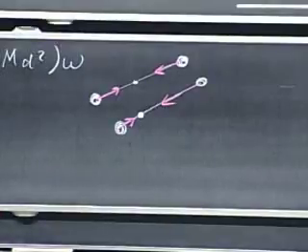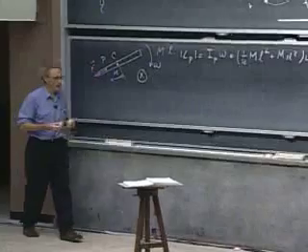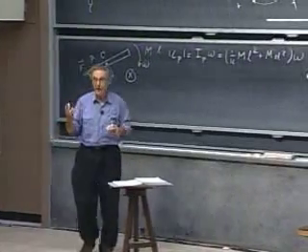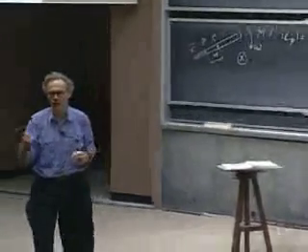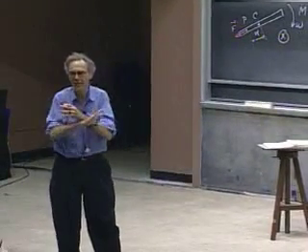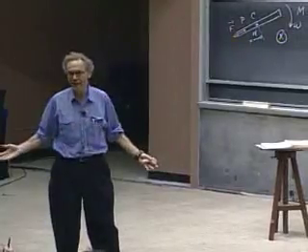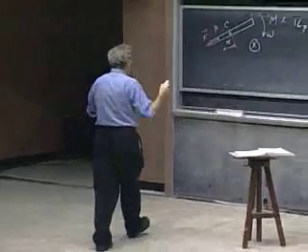It is because of the same asymmetry that you have here that there will be a force from the pin on point P. However, I don't care about that force because I'm going to take the torque relative to point P. And when I take a torque relative to point P, any force through point P has no effect because the position vector is 0. But I want you to appreciate that there is a force.